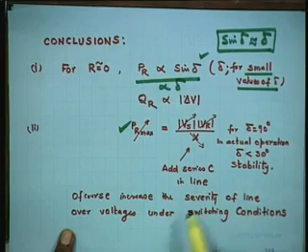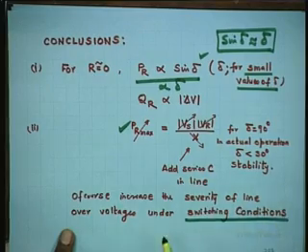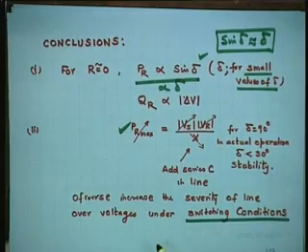What is the price here? The severity of line overvoltages under switching conditions increases, because you have to bring capacitance in and out with switching. Switching transients are covered in the same chapter 13 or whatever it is in that brown book, power system transients. You have to read that; switching transients are more serious than lightning transients nowadays. So, this or resonance, subresonance, these are the few problems associated with series capacitances.